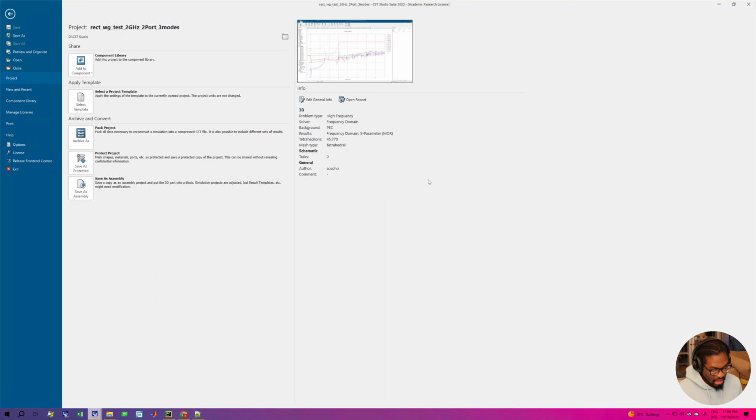Hello again. In this tutorial, I'm going to be modeling the Tesla cavity from start to finish. In my previous video, I think I just modeled for one cell, and when you extend that to the 9 cells without taking into account some things, you do not have exactly the same frequency as the Tesla cavity frequency. So, the classic Tesla cavity frequency, which is 1300 megahertz. In this video, I'll be going through the modeling, and I think I will have time to do a simulation. Maybe it makes the video long, but I would do it anyways.